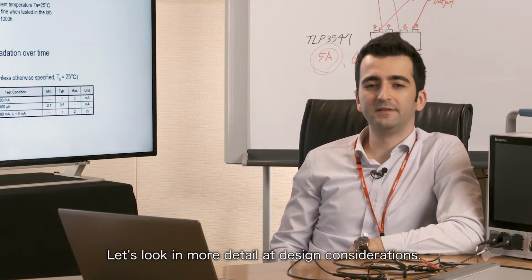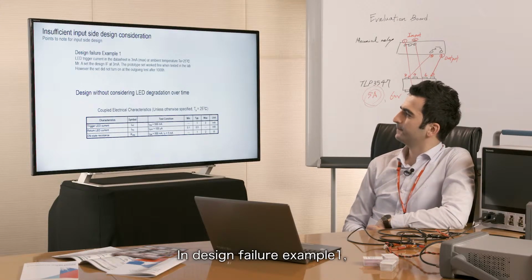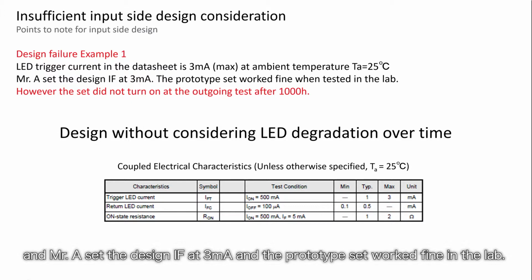Let's look in more detail at design considerations. Considering LED operation time of IF design. In design failure example 1, the LED trigger current in the datasheet is specified as 3 mA max at an ambient temperature of 25 degrees. So Mr. A set the design IF at 3 mA and the prototype set worked fine in the lab.